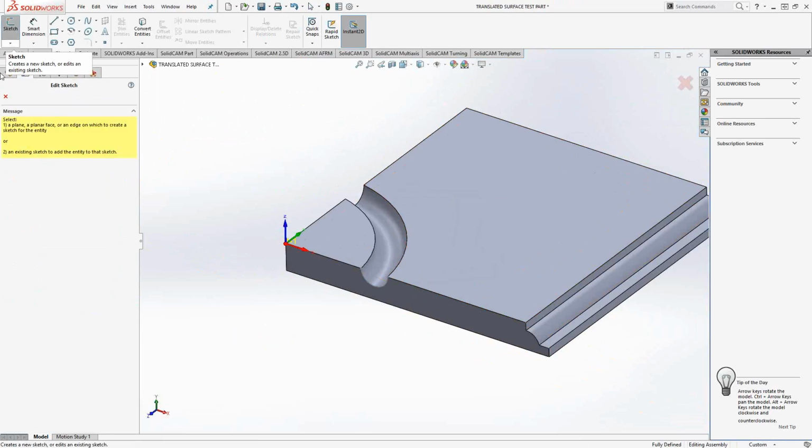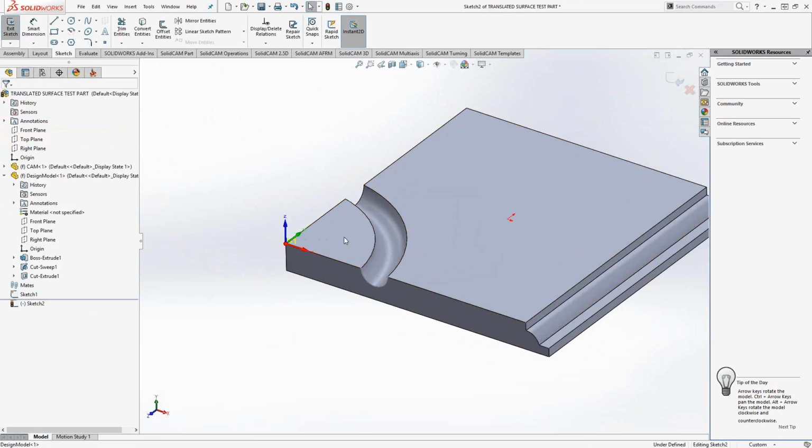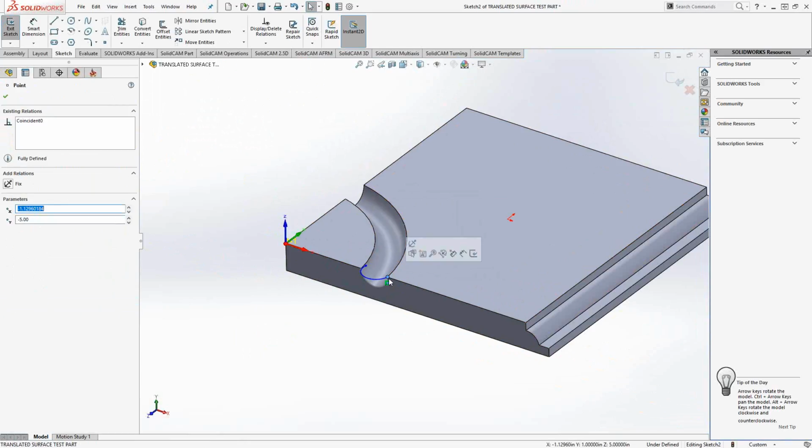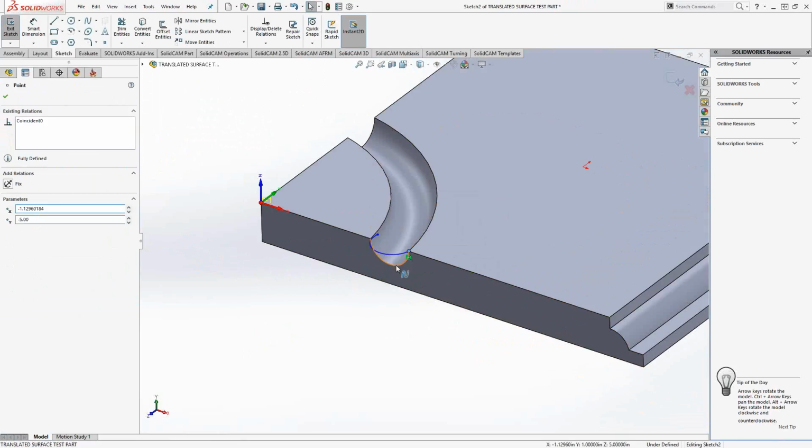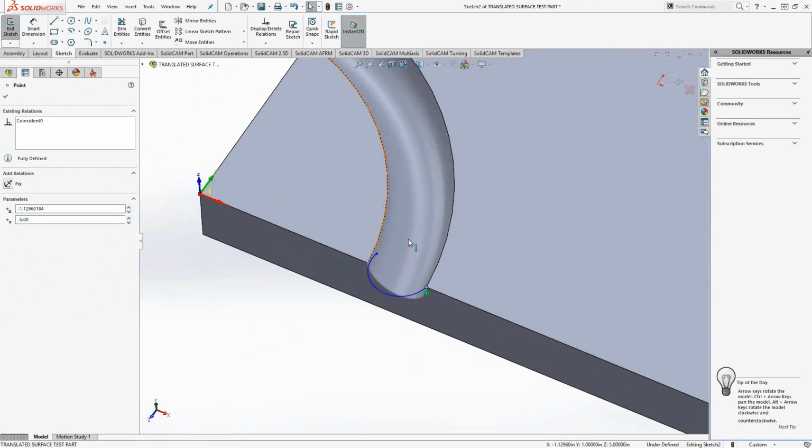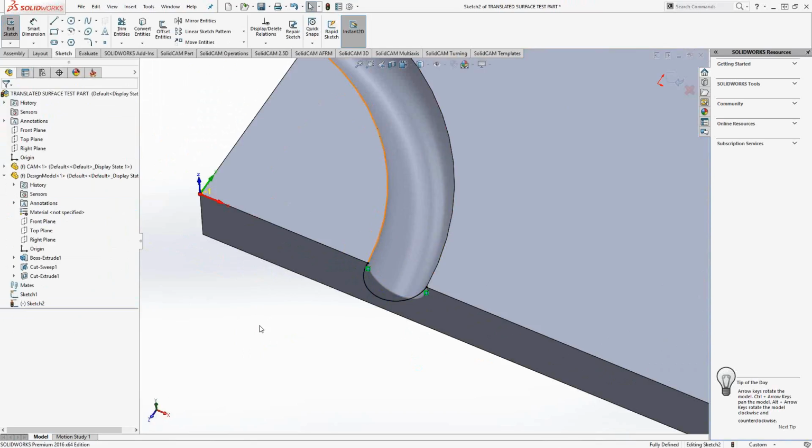Once again, I'll create another sketch, this time on this face, because this is the face where my path, my profile, is on. And I'm just going to do a Control-V, as in Victor, to paste it. I would like this cross-section to follow, let's say, this path right here. So I'm going to grab this and move it over here until they're coincident. Now I know that sketch is connected there, and I just want to clean this up a little bit by sketching it there. Perfect.